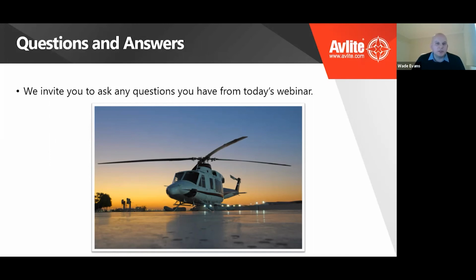So in order to be a compliant helipad beacon, it needs to maintain some pretty specific intensity and flash characteristics. And obviously, the trend in the market is towards more regulation and more certification. So we can't really provide that. Not being able to provide that certified fixture means we don't really want to integrate it either and support it going forwards, because it's ultimately a non-compliant build. So rather than doing that, we source an appropriately certified version of it and integrate it accordingly.